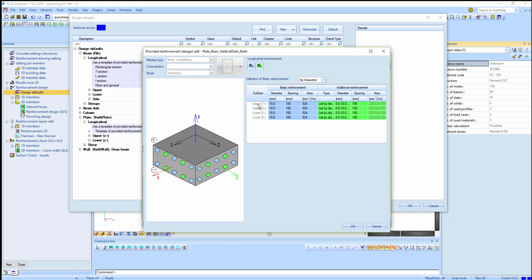In my case, let's talk about this example. We said for the top reinforcement 1 plus, we need 508 or 06. So what I'm putting here as a constant amount, 524, this is too much. So I will say 0. Don't put anything on the top side. And if the 0 is not enough, then I can use different possibilities from here by fixing the amount. If the 0 is not enough, then put diameter 10 with the spacing 150. This should cover.